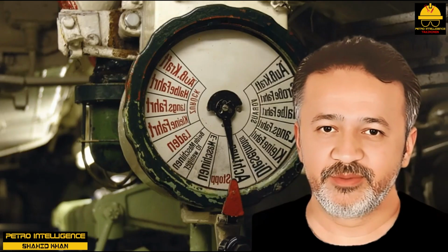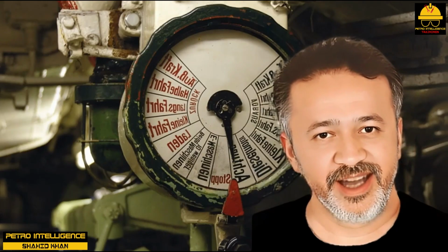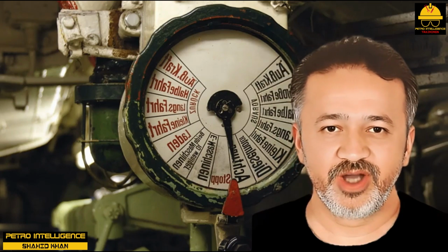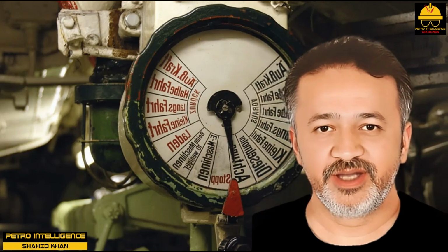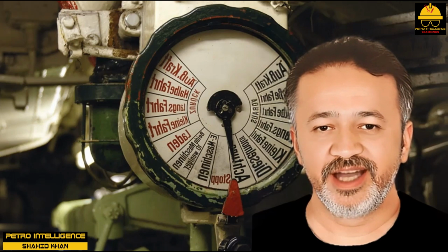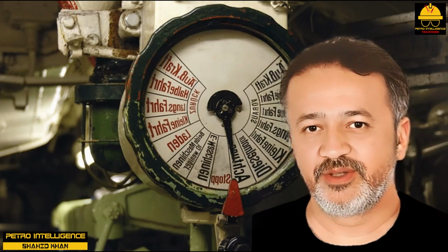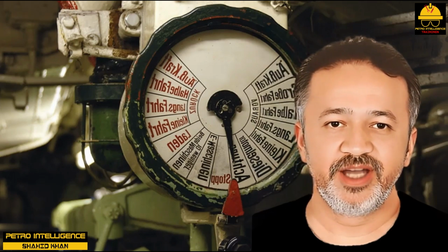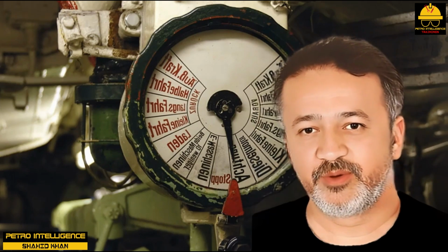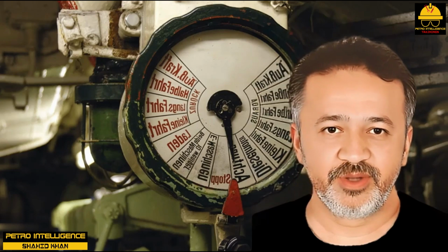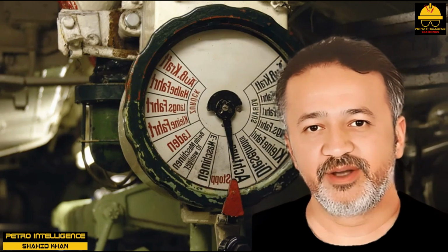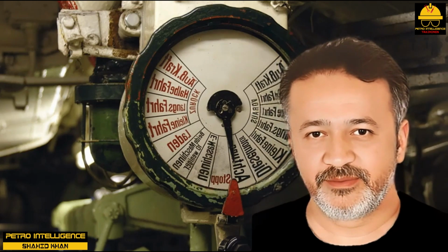The most common type of automatic valve is a globe valve because of its versatile on-off or throttling feature. Control loops use on-off or throttling type valves to regulate the flow of fluid into and out of a system. In addition to the pneumatic, electric, and automatic control valves, there are also spring or weight-operated valves. Spring-operated valves hold the flow control element in place until pressure from under the disc grows strong enough to lift the element from the seat. A check valve would be in this category.